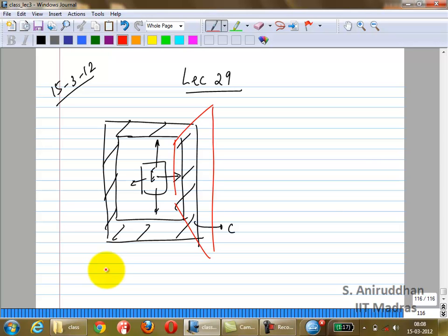You'll see this as we start looking at the op-amp stage by stage; one of the stages uses something like this. This is an example of a donut layout, and it gives you larger beta.